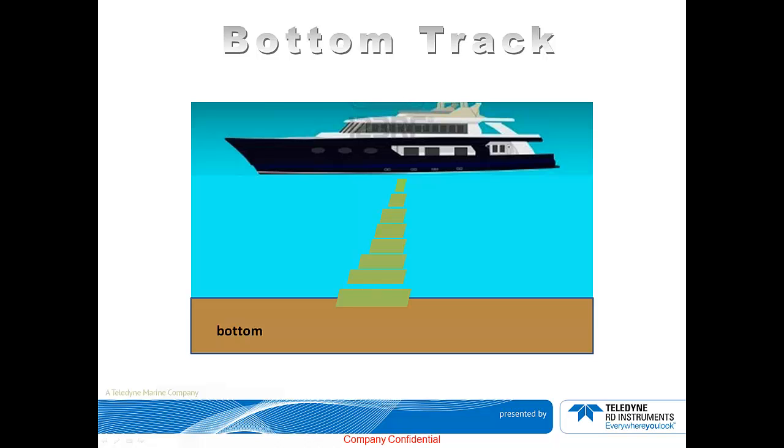But where is bottom tracking really used, and why is it important? It is important because it makes the measurement of speed over ground or speed through water, altitude or range to bottom, or distance made good, among others, possible. In the following slides, we will try to understand what makes bottom tracking work and how it is best optimized for various situations or sites in which your DVL is deployed.